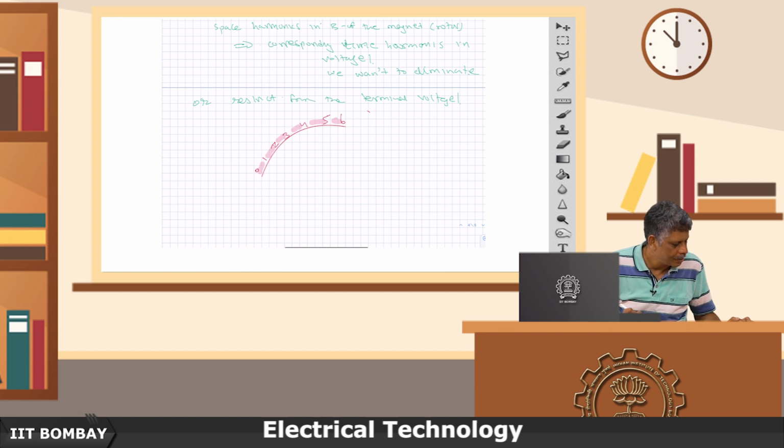I keep a gap of Lg, let us say this is my air gap Lg here, then I keep it steady for a couple of sections, then from 4 to 2, I taper it down further.